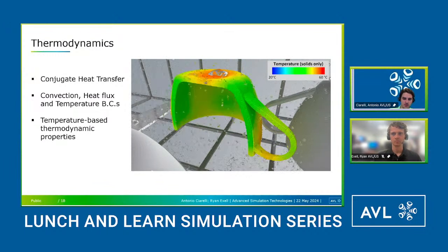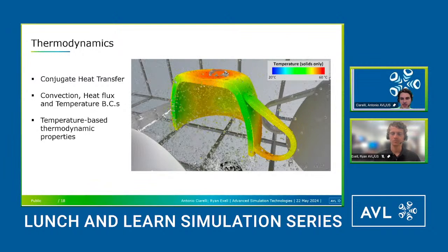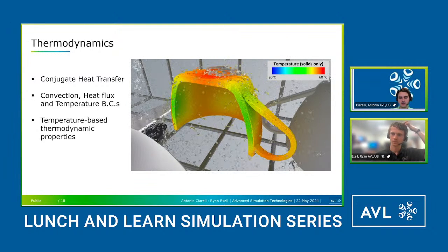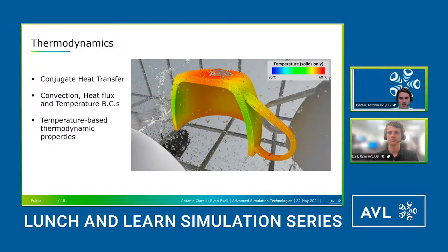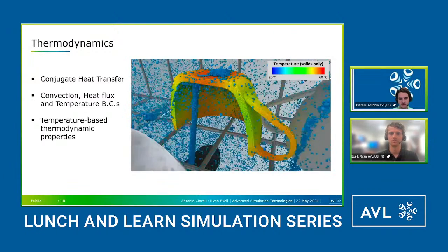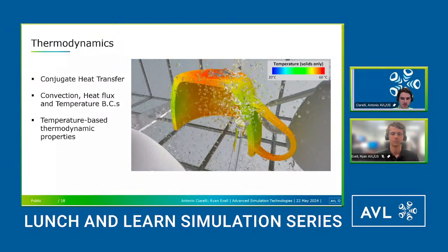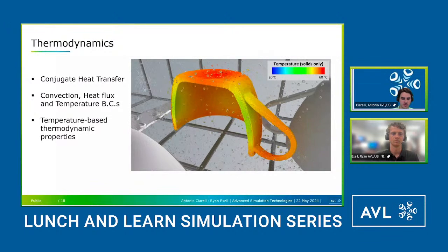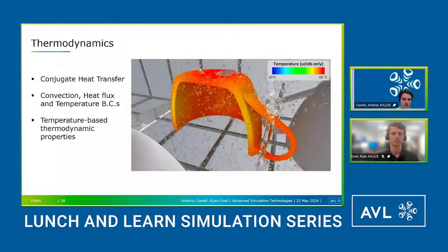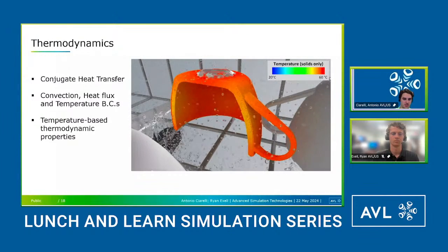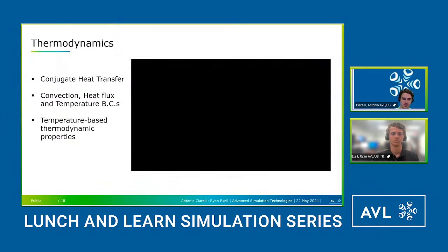So you have the outer shell of the CAD, but then you also fill the CAD in with solid particles that you can set these properties for that allow you to get the temperature gradient that you would need to solve for based on the temperature of the fluid and then the steady temperature of the cup at the initial, and then utilizing those boundary conditions and heat transfer settings to get accurate results to see what would happen during the course of the simulation.